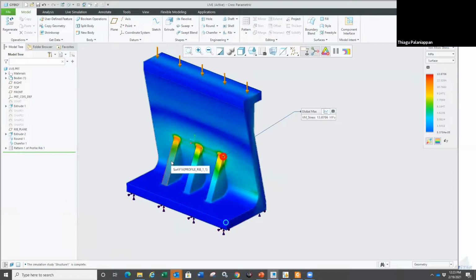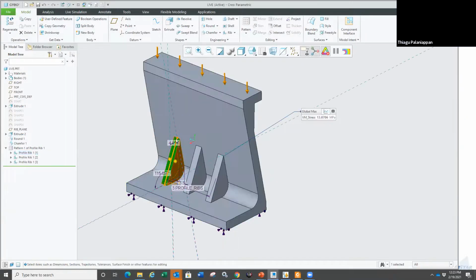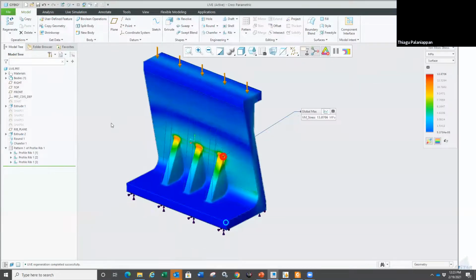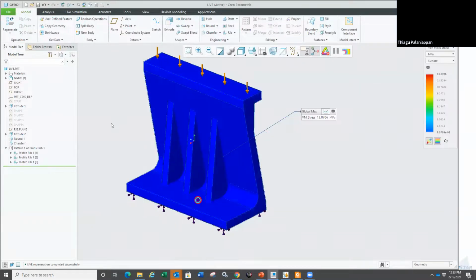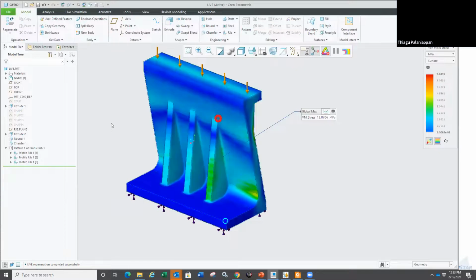And I'm thinking, okay, all these are common sense design things that we normally do, right? But we have to have an idea of what's going on, what is the stress, what is the deflection. Maybe I'm going to increase it a bit here, and we'll see if that helps. You're adding more material and a little more stiffness due to that geometry there. It's making it a little stiffer in a sense. And that did bring it down to 6.7 megapascals.